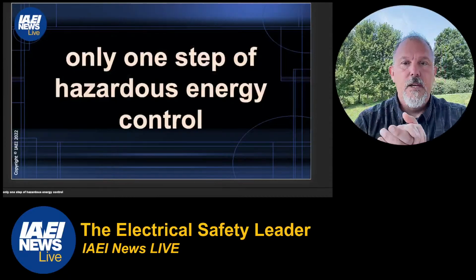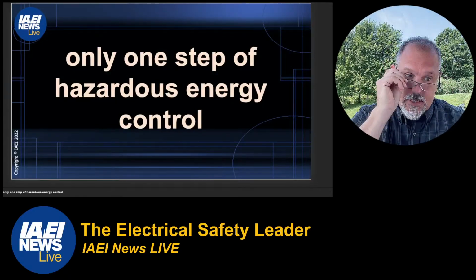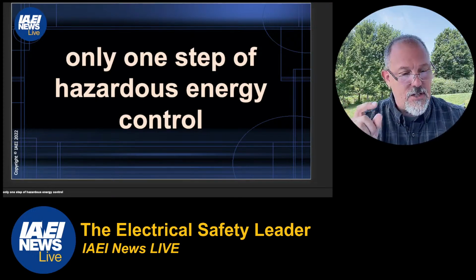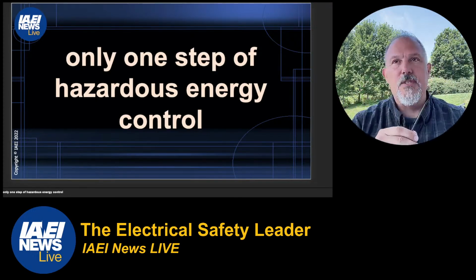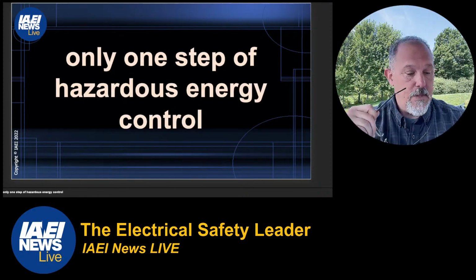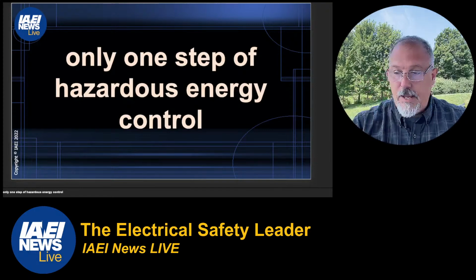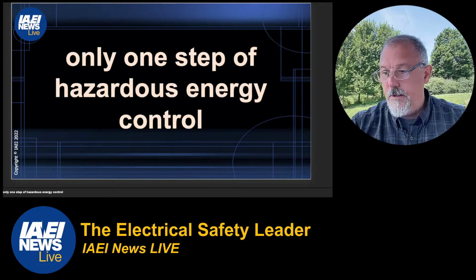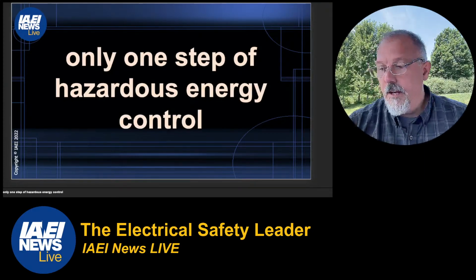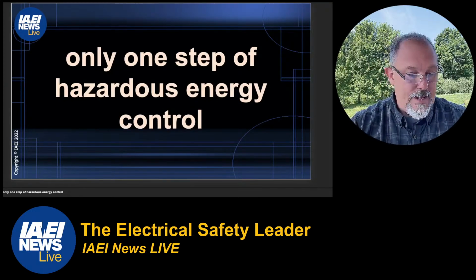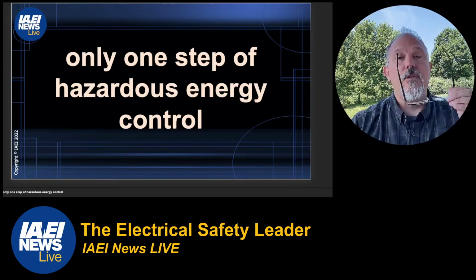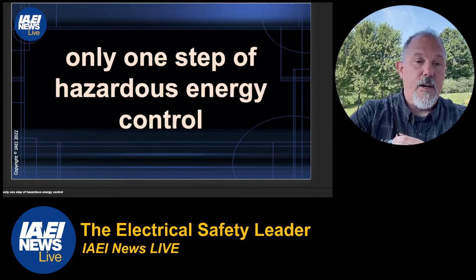Now another aspect to remember, Carly, is that I've heard people say, hey, you have to just make it safe, turn it off, and that's what you have to do. In reality, it's a lot more than just turning something on or off. There's an entire process around establishing an electrically safe work condition, and lockout tagout is just one step of controlling hazardous energy.